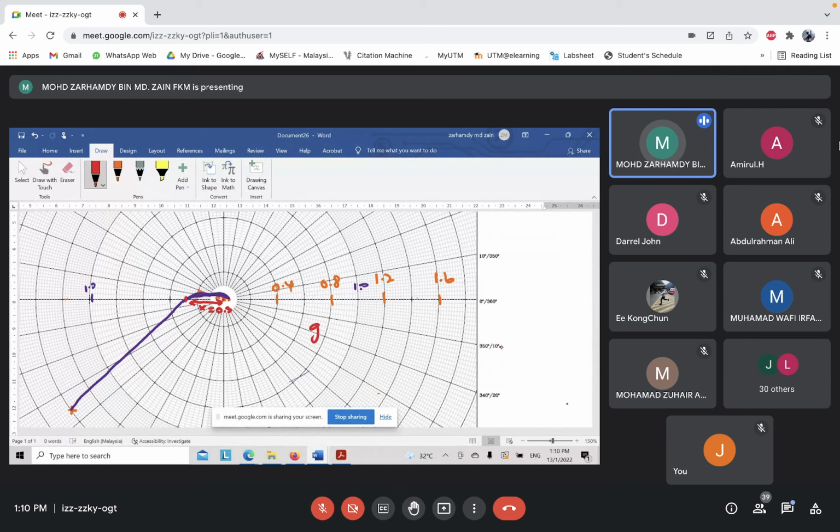Okay. Our gain margin, the formula is GM, gain margin, and we call GM equal to 1 over X. Where X is the range, this length, what do you call this, the distance, the intersection distance to 0. So now we have gain margin is 1 over 0.3. So what will you get? 3.333 so far. Okay. So this is the gain margin.